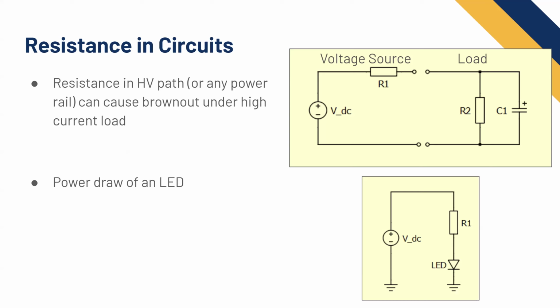But this is one of the downsides of real power sources. So it's something to think about. In terms of cars, you would have something in the throttle controller to reduce the amount of throttle you're commanding in order to reduce the amount of current that you're pulling so that you don't brown out. Does anybody have any questions on that before I go to our next example?